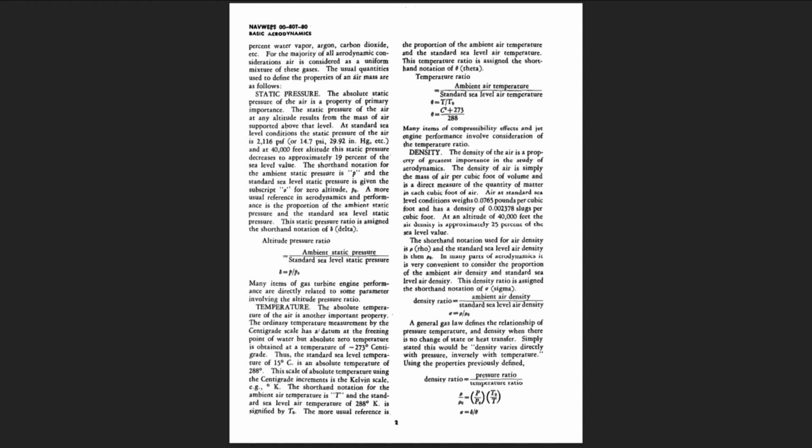Temperature ratio equals ambient air temperature over standard sea level air temperature, or lowercase theta equals uppercase T over uppercase T naught, or lowercase theta equals degrees centigrade plus 273 divided by 288. Many items of compressibility effects and jet engine performance involve consideration of the temperature ratio.